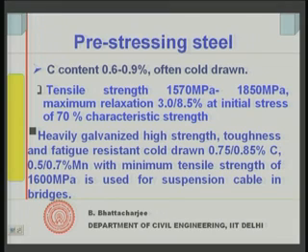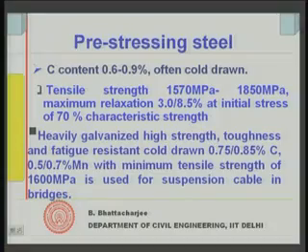other types of high strength steel in suspension bridges. Now it is clear why we use manganese, because it will make the steel ductile, and it has to have high strength. Therefore, we use a higher percentage of carbon here, and then again they are cold drawn.